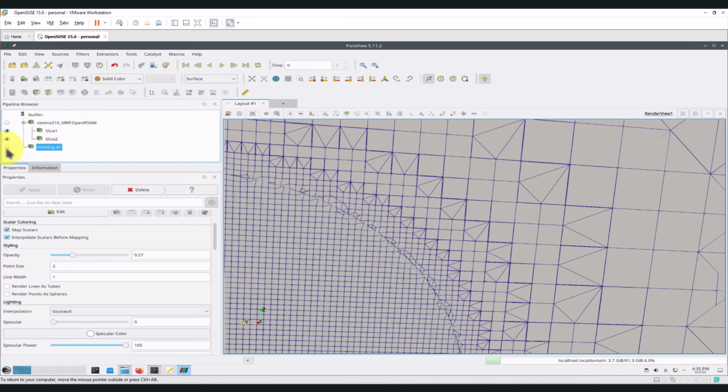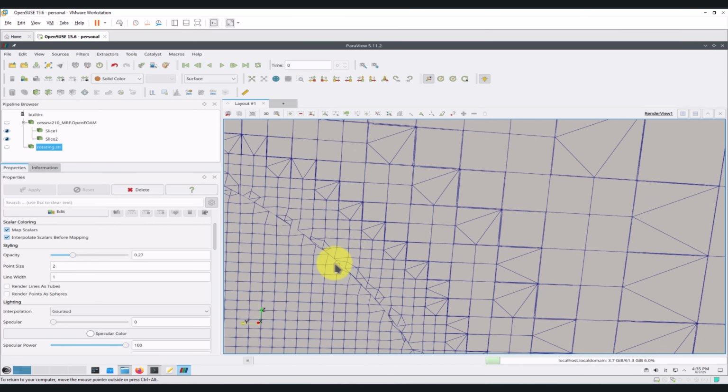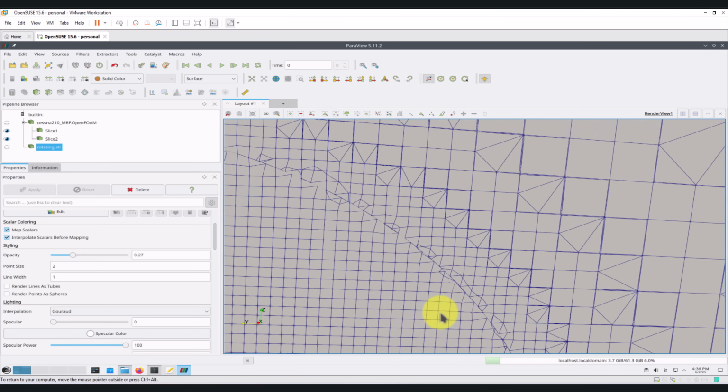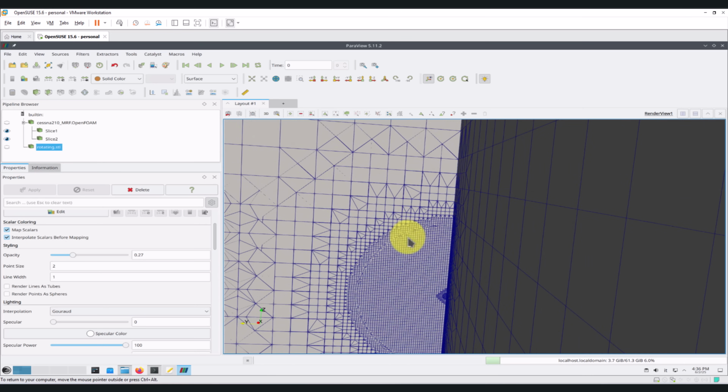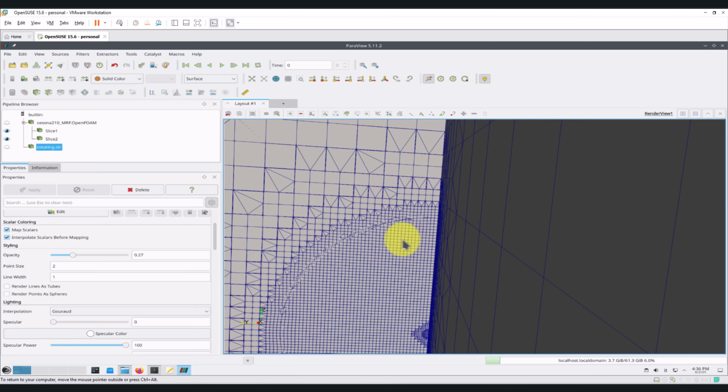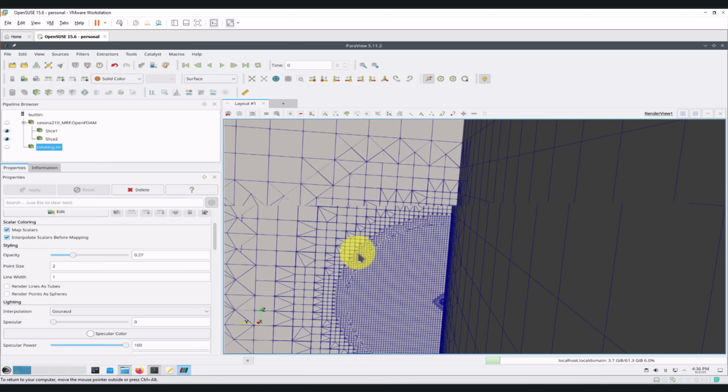That's why I say that sometimes it's good to increase the feature in the edges, also to add the edges to resolve the edges in this region better, to avoid these issues. It's difficult to control, honestly, in snappyHexMesh. I don't know the reason, because it should be perfectly matching, but for some reason you don't get it.